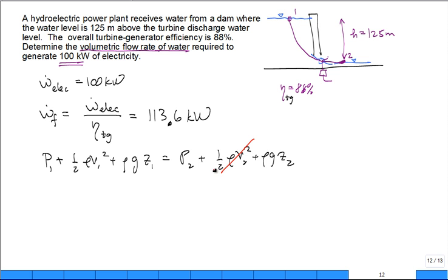What about these speeds? The discharge speed at the lake at the bottom is negligible, and the ingestion speed at the top, the beginning, is negligible. Both are at atmospheric pressure. But one thing I forgot in this equation is that the streamline has to go through the turbine, does it not? So you have the pressure extracted by the turbine.